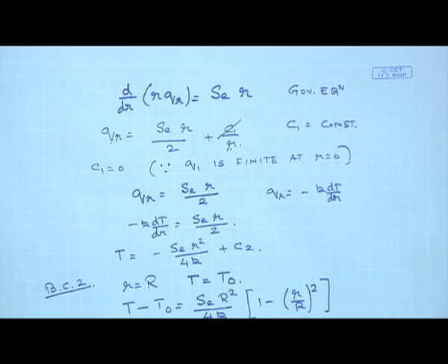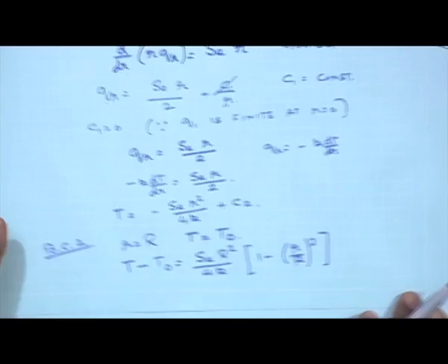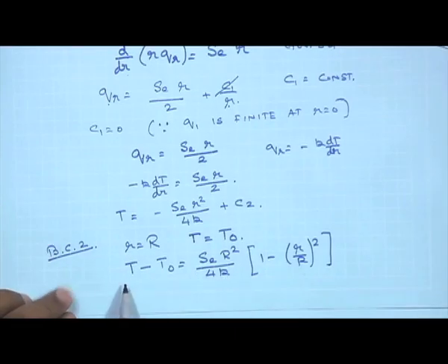So what you see here, I'd point to this equation once again. The temperature distribution, which is a function of r, where T0 is the temperature at the outside of the wire, is a parabolic function of r containing terms such as the thermal conductivity of the solid wire and the heat generation per unit volume due to the passage of current through it.